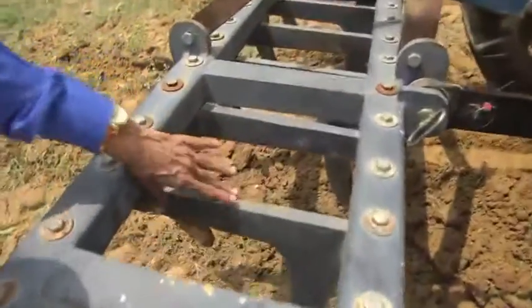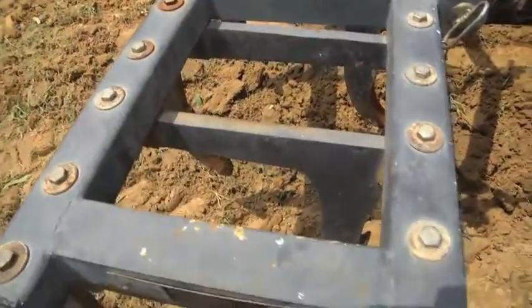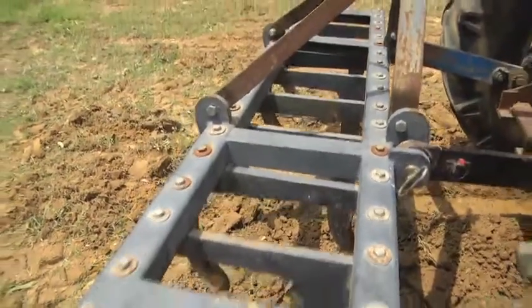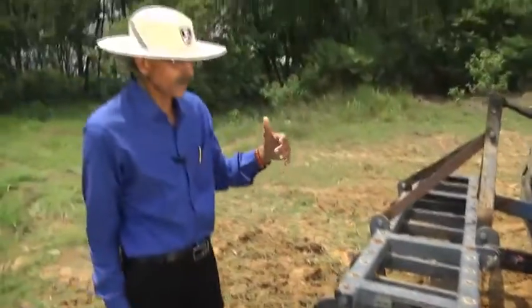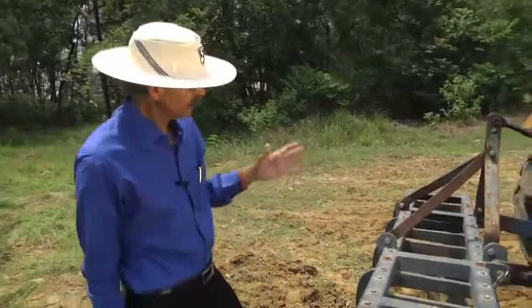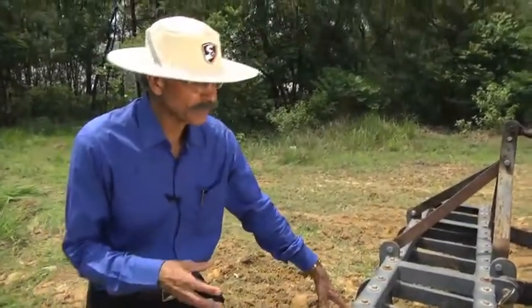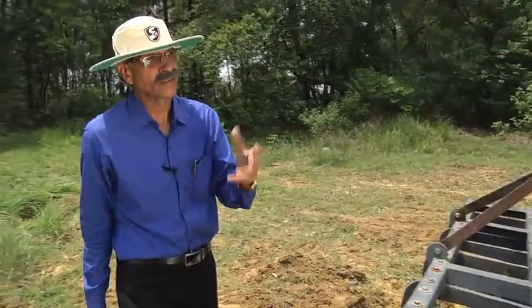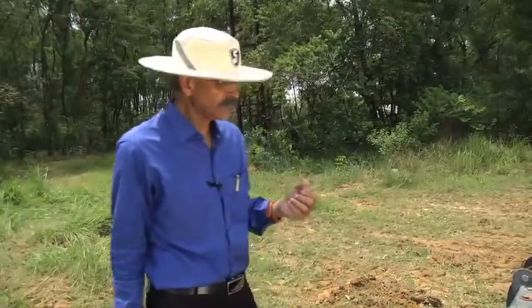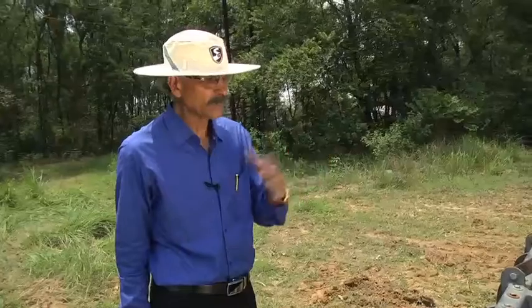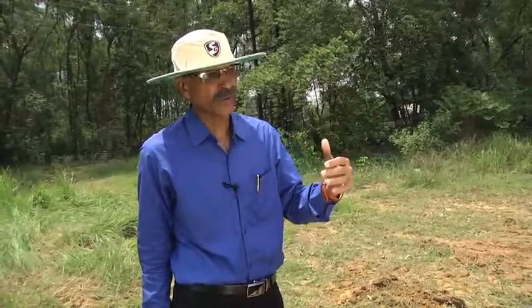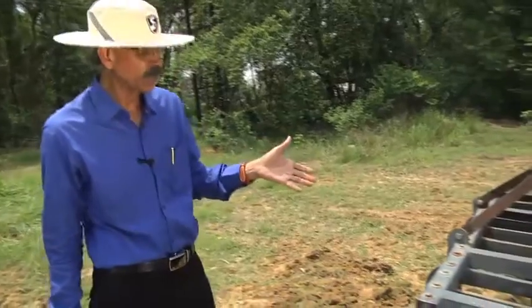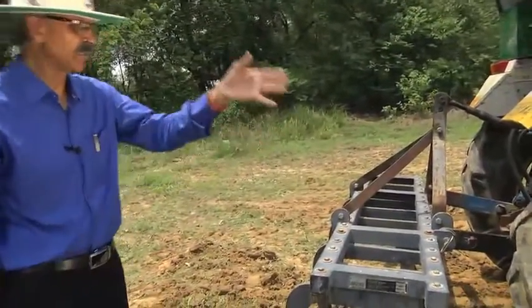This is a rigid one, and the job of this is to break the clods which have been prepared by the moldboard plough or the disc plough. Now, for actually preparing the field, at least twice operation of this will be required, as you have seen in the case of a rotavator. So, definitely it requires more energy as compared to that, but in conditions where we have to prepare the field after first ploughing and second ploughing, which has been a virgin for a long time, then you will require the operation of this. We will see the operation of this as it is mounted and connected to the tractor.